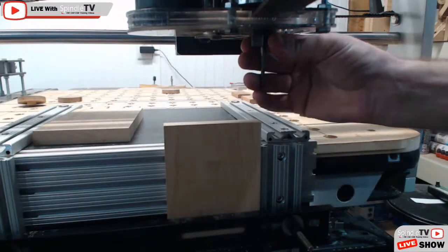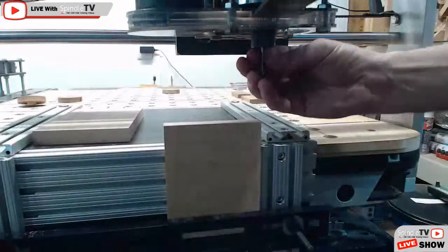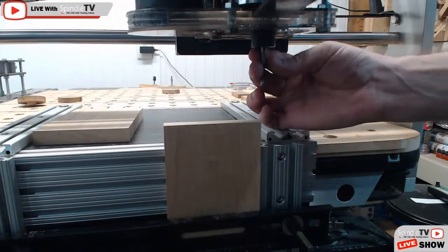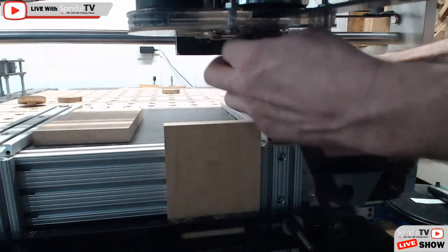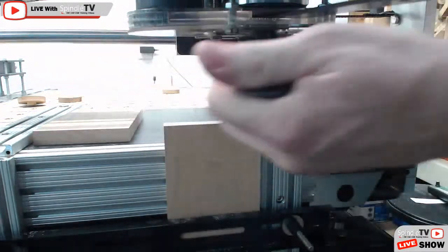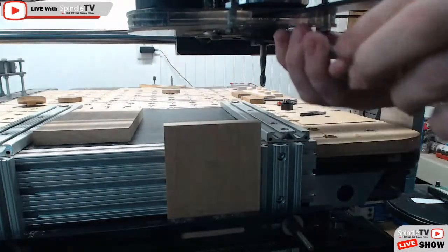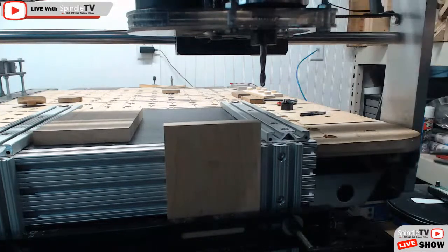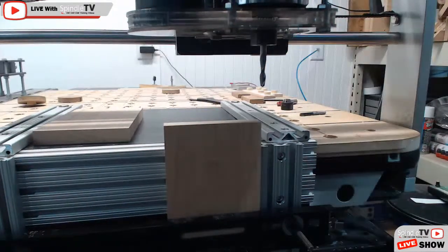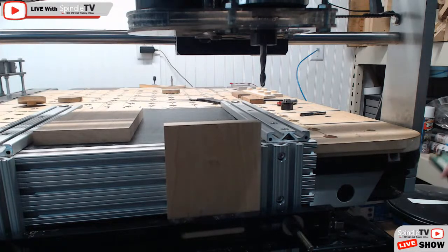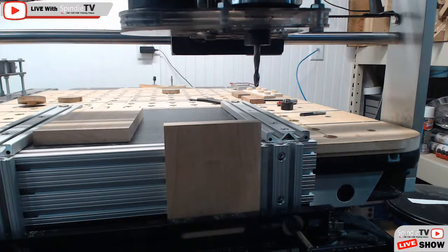Let me get, you don't want to come to the top of the flutes. I don't know how well the shading shows, but you want about 1/8 inch or 1/4 inch of that shank showing. I usually go 1/8. Now, the cool thing about the dovetail bit, it actually shows where the bit should be inserted to. All right, so now that I have that, I'm simply going to use my little feeler gauge touch plate to touch off the Z.